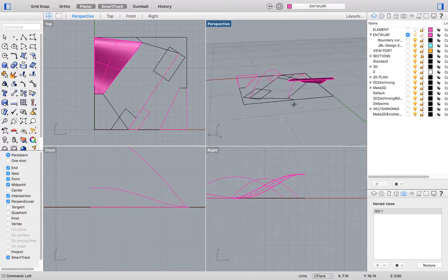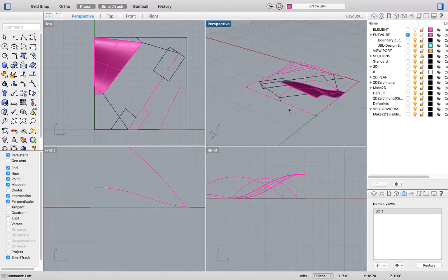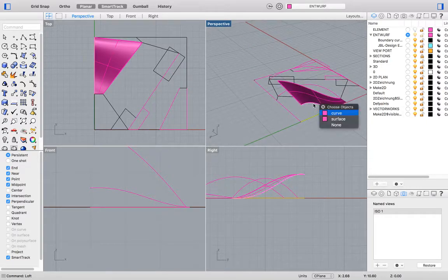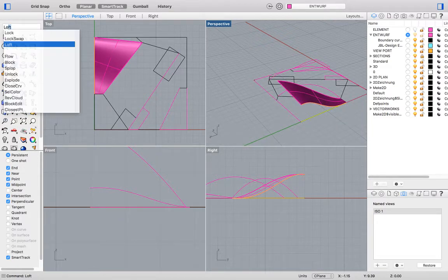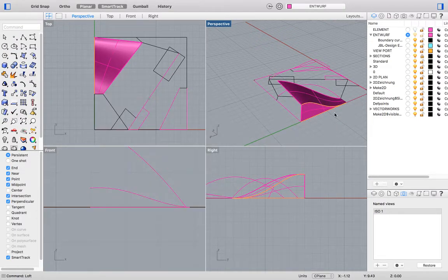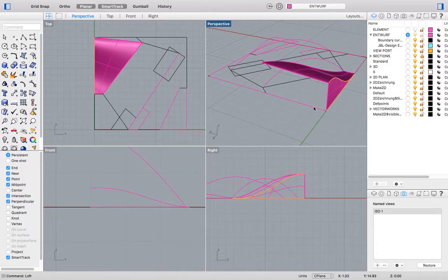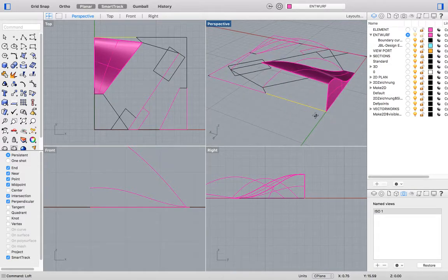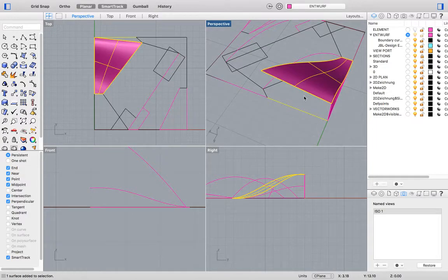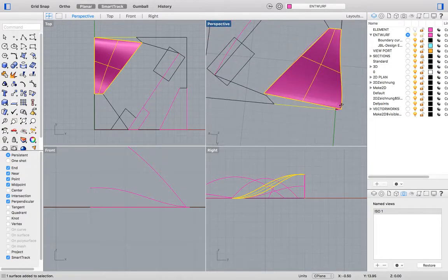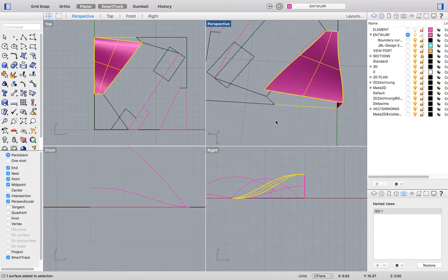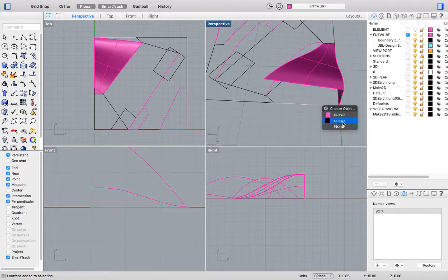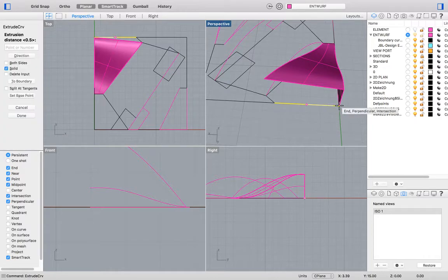And we want to make a closed extrusion again. Okay. So we're going to select this curve, and loft. Enter. Select this curve. And again, we don't have a curve for this front piece. So we're going to extrude the base curve by typing the command extrude curve.